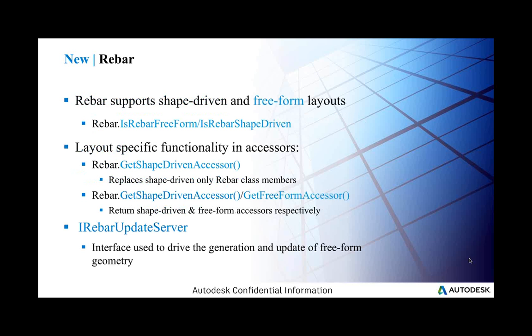From the structural side of things, there are a number of changes to the rebar element. The rebar supports both shape-driven and freeform layouts now, and accordingly there is a possibility to query what kind of rebar it is, whether freeform or shape-driven. The layout functionality is driven by accessors. There's a get shape-driven accessor to replace the shape-driven only rebar class members, and the freeform accessor to drive the new freeform rebar style.